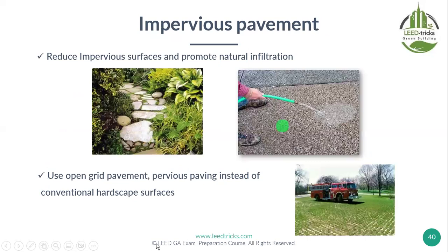Here we can see that even if you make paving or concrete, the water will not stay, it infiltrates easily. So material selection matters. When you design a walkway, design it this way, segmented, nice, very comfortable, and so on. So water can still infiltrate. It's not totally concrete.